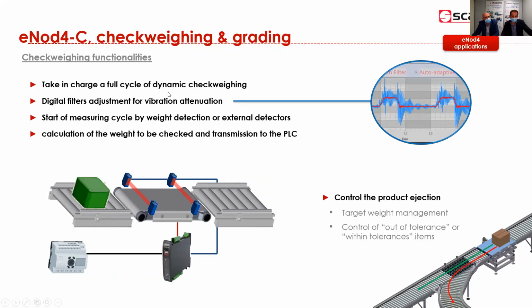Of course, in the eNod4, especially in this eNod4C firmware version, you have the possibility to define the timings: the settling time, the measuring time, and some delays in your process.